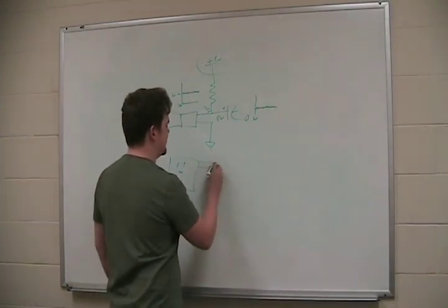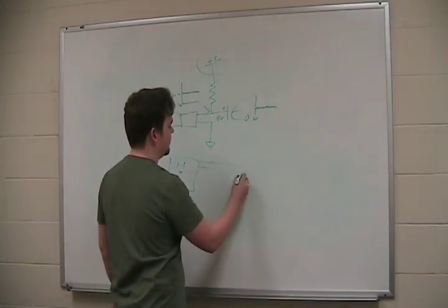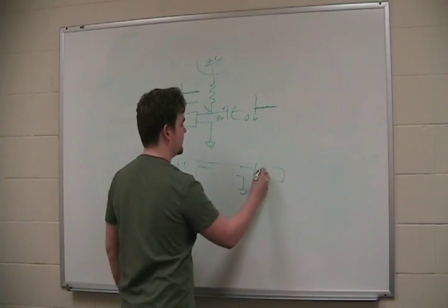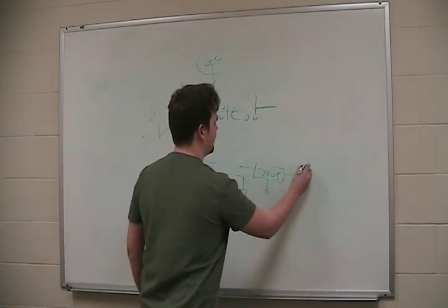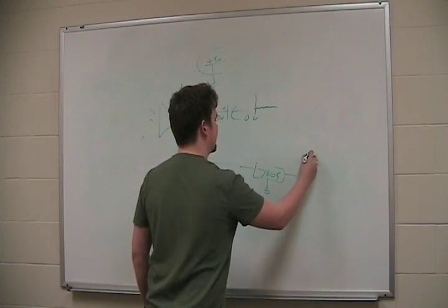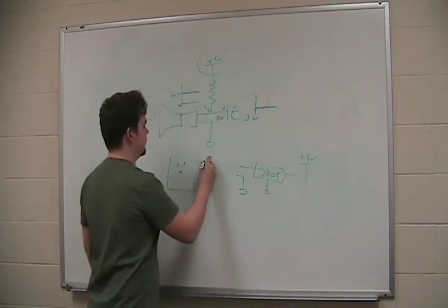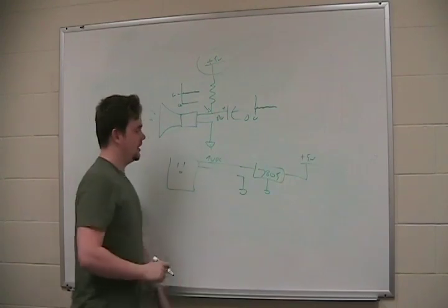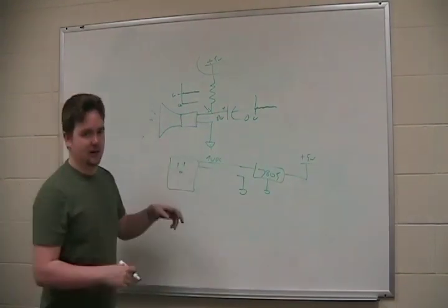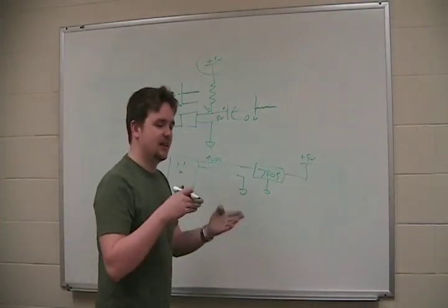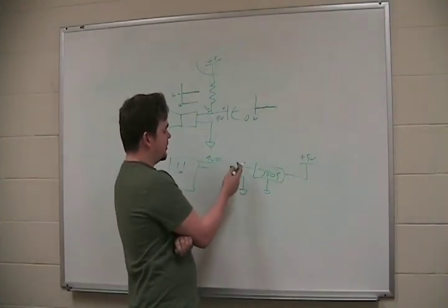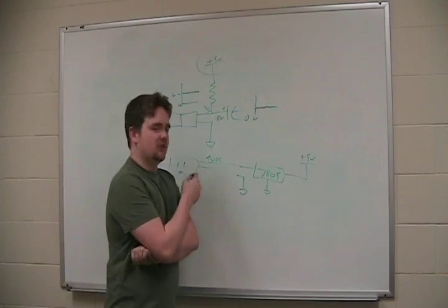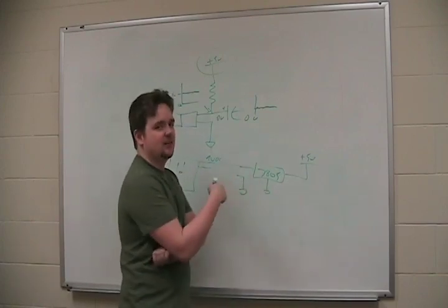But when you plug it into your circuit, say I wanted to plug this into a 7805. Now remember what a 7805 is. Say we've got 9 volts DC here because of that wall transformer making the power supply for us. We can't rely on this thing not to give us a whole bunch of noise. We're going to get a DC, but we're going to have an AC component with it.